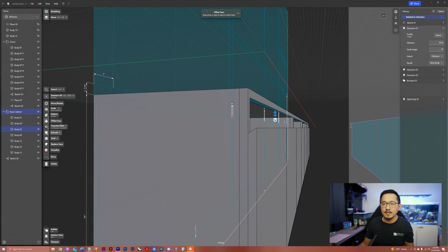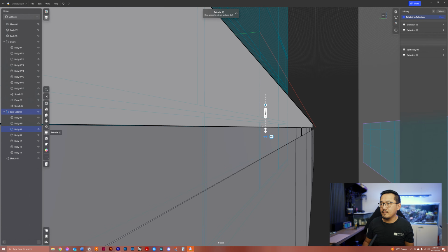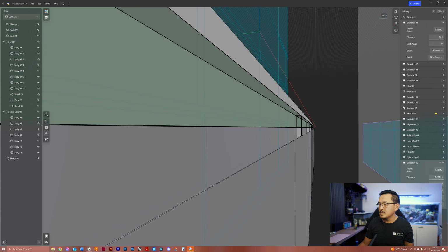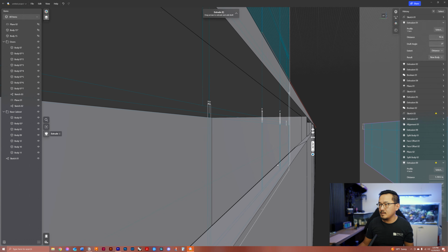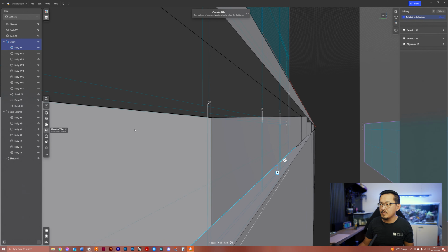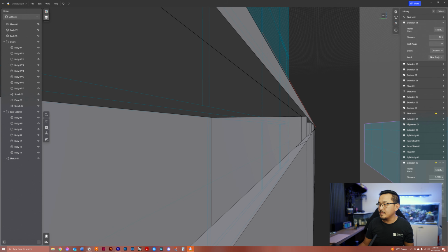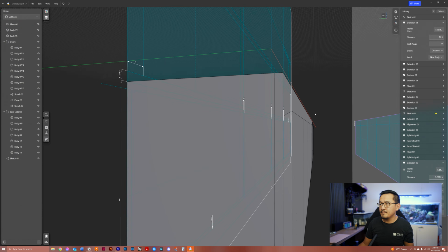And then we're going to hit the extrude button and go down to whatever given point. That is because we can go back to our extrusion here, change our extent to point, and the point is to be right below the ledge so that we don't see into the space, see into the cabinet box. There we go.